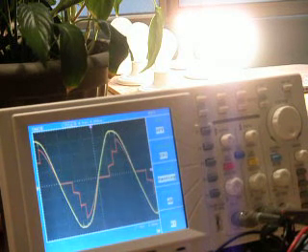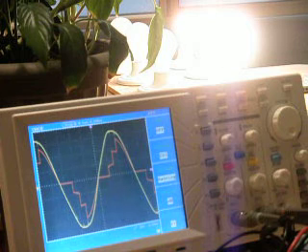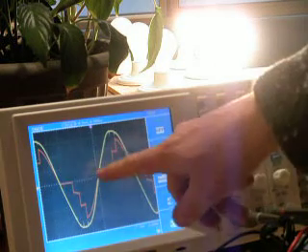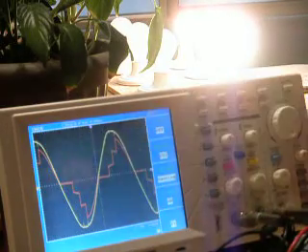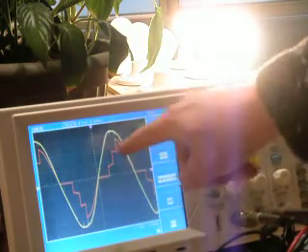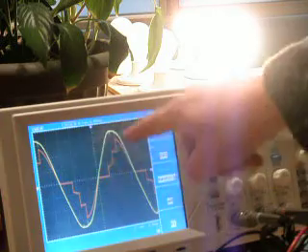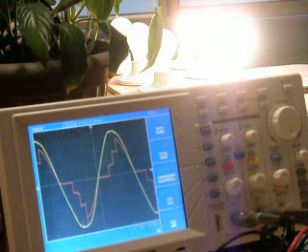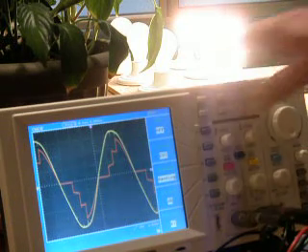So that's what it looks like when you have three light bulbs all being controlled by different controllers and switching at different points on the current spectrum. So we can see that during the current flow we have these interruptions where the lights switch off, and it's very much a stepped waveform. And you get some very interesting waveforms around lamp dimmers for that reason. And I'm going to show you the frequency.